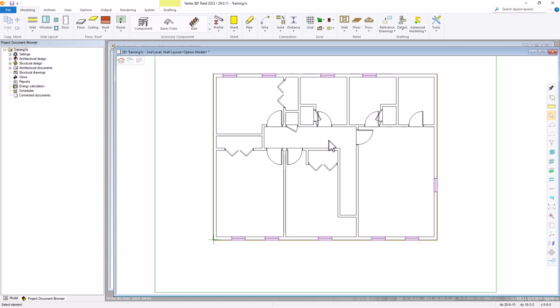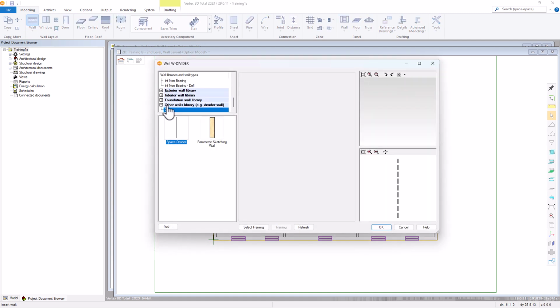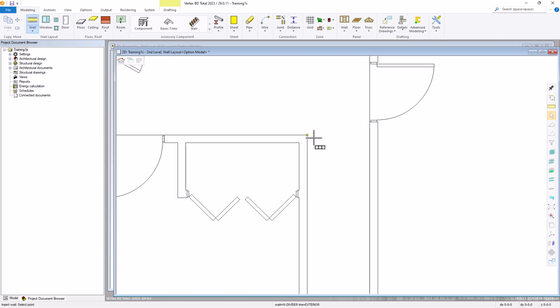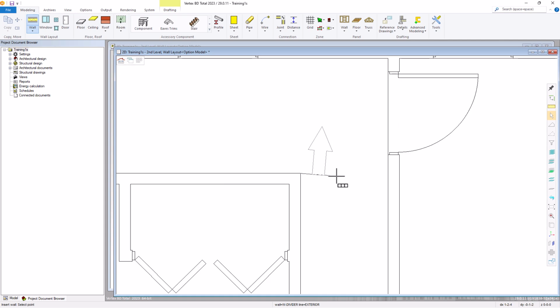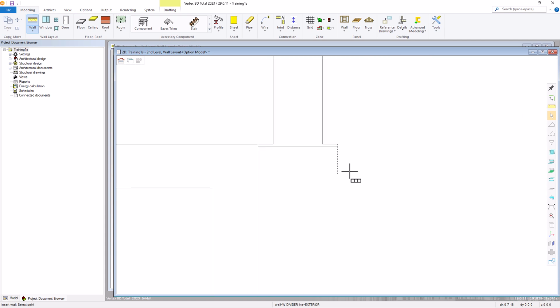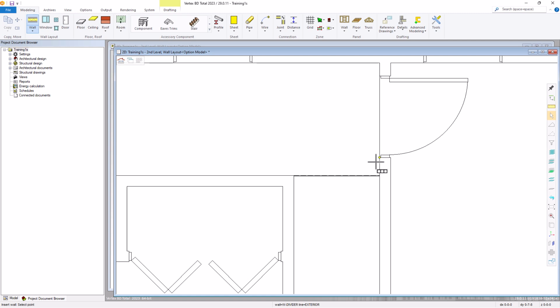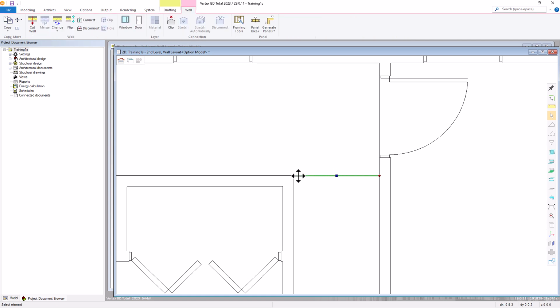Now most of the rooms on the upper level are clearly defined, but we want to omit the stairwell from the hallway upstairs. So let's go ahead and add another divider. We'll just run it from this corner across. Go up to Wall. In the Wall library, we'll go down to Other, select Space Divider, and select OK. Zoom in, click on that corner, lock the horizontal constraint by hitting the U key. I'm going to zoom in and make sure that it's offset correctly, and it is. So we'll run it perpendicular to that point, and now we'll hit Escape, and we'll create our T intersections.